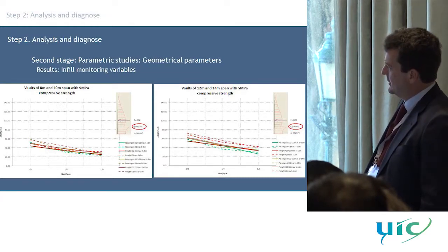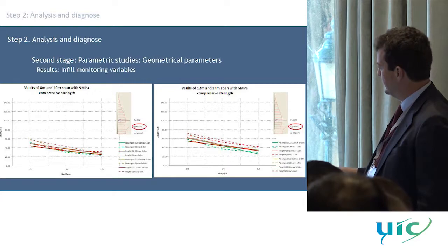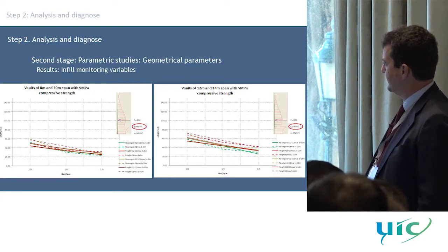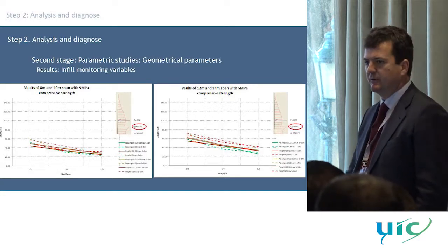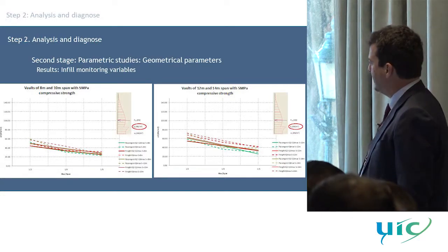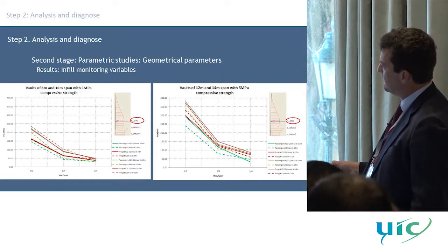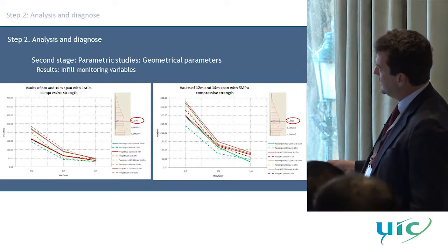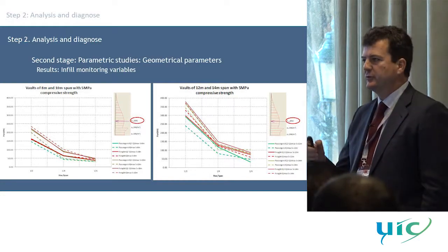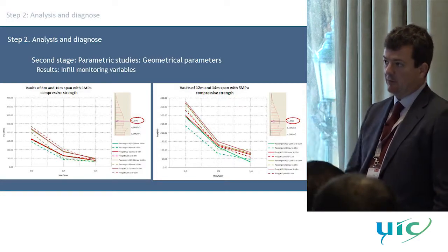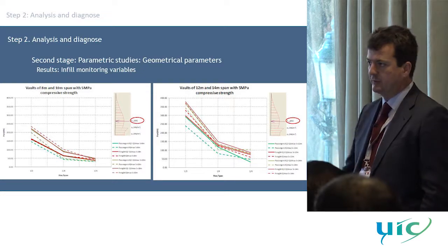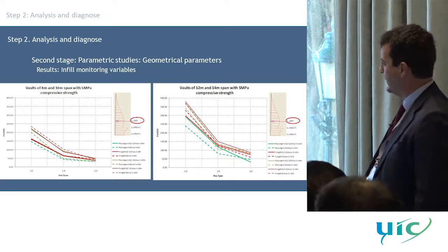Here again, this is more or less what we have on the one side. Of course, if you have a very shallow arch, you're going to have less horizontal effort. Here you can see the different values for passengers, freights, whatever. So again, all the results were quite predictable, but here we have about 400, 500 kilonewtons for 2.5 meters of width. So it's not a lot, again, of horizontal reaction for an abutment or for a pier.